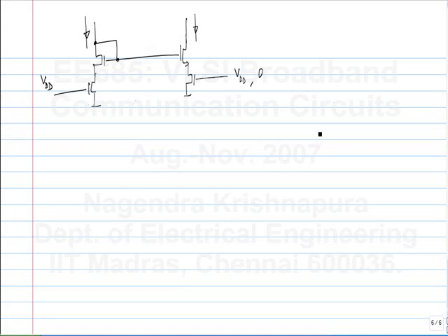Okay. So the capacitance that you see at this node will be the capacitance of this device. Is that the only thing? GMR times this capacitance. No, you will see the capacitance of this device directly. Okay, and you will see the capacitance of this attenuated. Okay. So that's fine. Is that the only thing? Compliance. Compliance reduces because you still have this voltage drop.